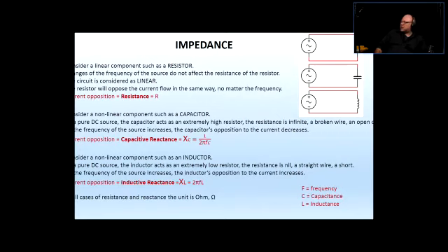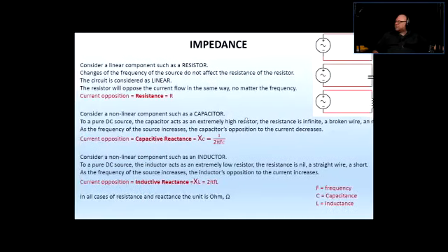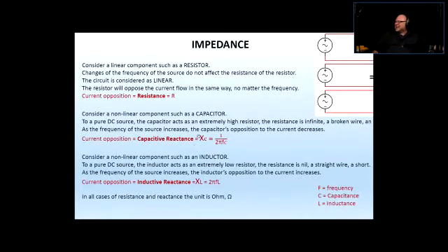Now let's take a look at the coil or inductor. Oh, the capacitive reactance, it's a resistance, reactive resistance, reactance. We don't designate it with R. We're just going to go XC. Right? So that's the reactance of a capacitor. And the amount of capacitive reactance is equal to 1 over 2 pi fC, where f is the frequency, C is the capacitance of the capacitor.